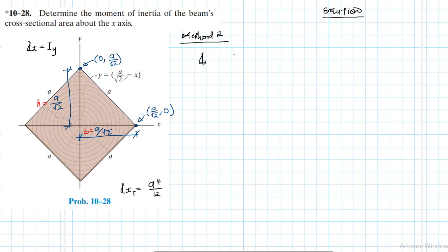So moment of inertia about the x-axis will be equal to integral of y squared dA. So let's get a very small area again parallel to the axis of interest. Okay. So this one we just want to find for just one triangle, and its differential thickness is dy.